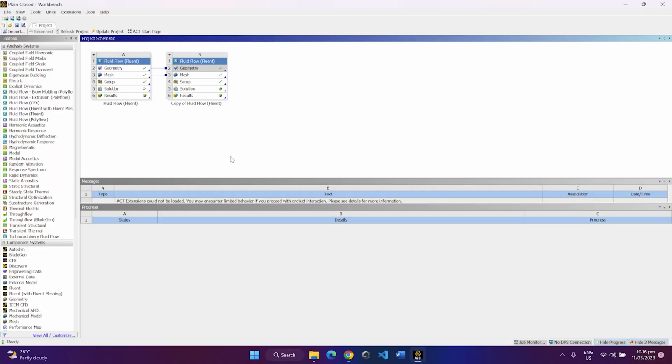So in order to start off with Ansys Fluent, after you have modeled the domain for your simulation, you simply start up Ansys Workbench with whatever version you have. And from there, you will be greeted with this screen as can be seen below. Now, these two components would not be here normally, but they are here for the sake of demonstration. So how would you add your own fluid simulation?